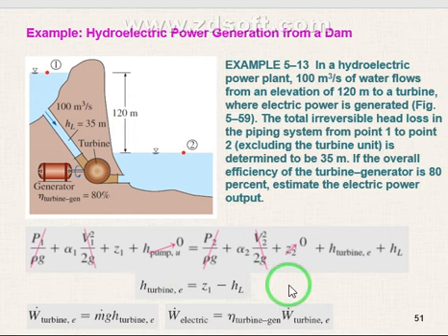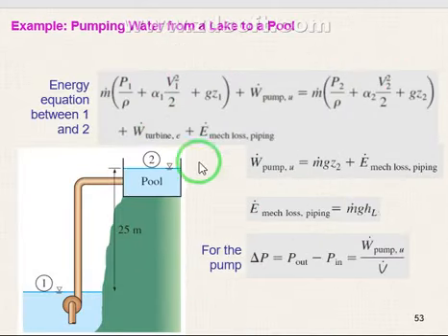It's interesting, we have two equations to know how much work is produced by the turbine: W turbine = m dot times g times H turbine. So from this equation, we're going to get H turbine, then we take it here to know how much energy is produced. Then the net electrical energy must be multiplied by the turbine-generator efficiency, which is 80% here. Right, so go back here to the equation.